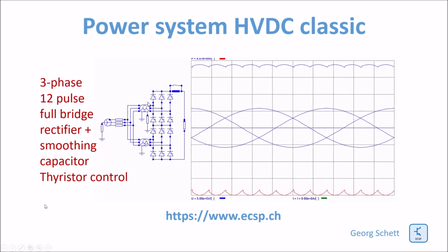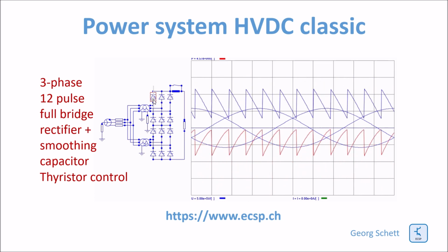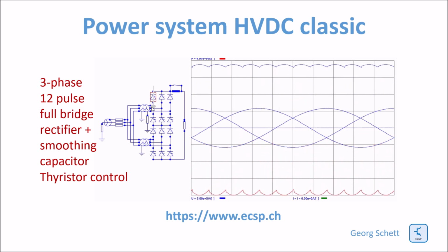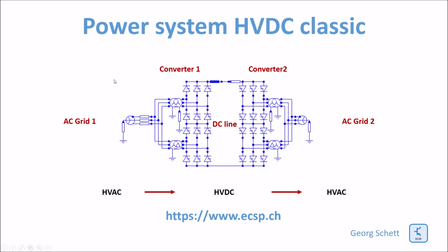Here, look at how it works. You can see how I can control now my HVDC. And if I insert the reactor, the DC is now pretty smooth. The curves jump a little bit because of the automatic adaptation of the resolution. So this is now really the converter we will utilize for an HVDC system.